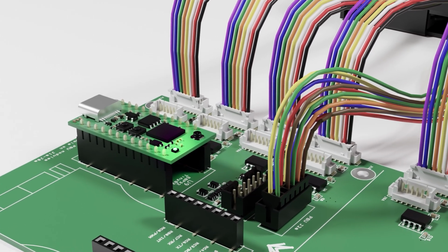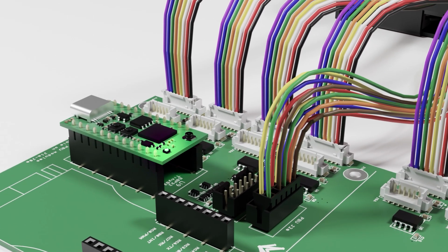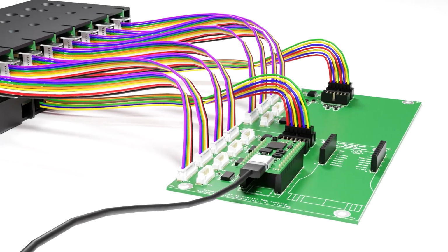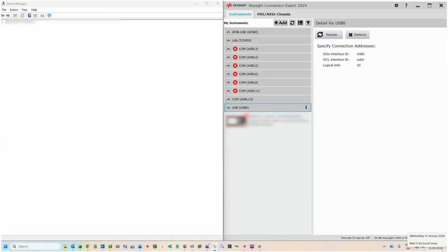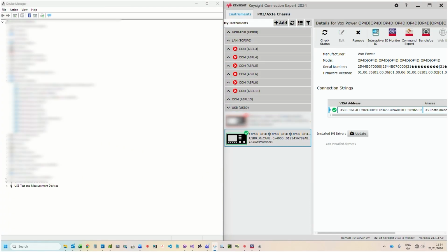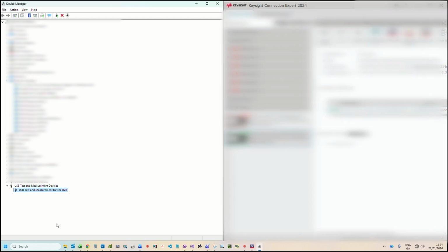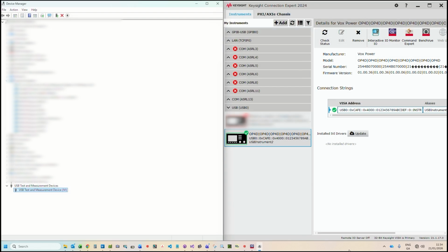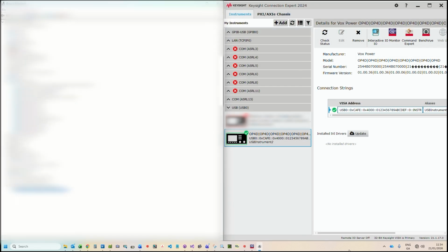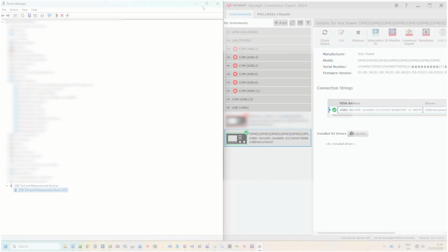At this point, the Wi-Fi signal and USB device will become active. If you are connecting via USB, the interface will appear on your PC. You can see the device in the Device Manager. Utilize VISA software such as IO Library Suite from Keysight to communicate with the DevKit.